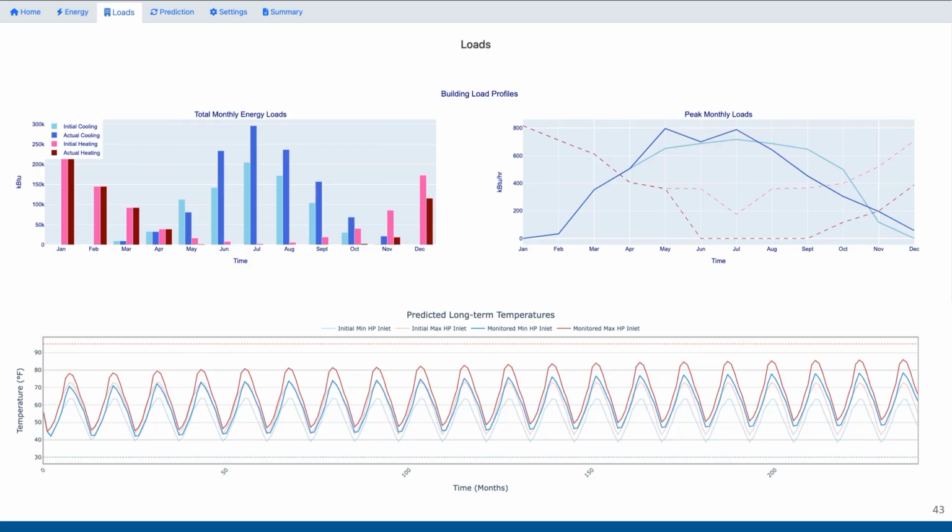that engineers can use. And then furthermore, your favorite ground heat exchanger sizing software uses algorithms to calculate the future design temperature of that ground loop. And I'll give you a little insider hint, those models are wrong, right? But it's a question of how off they are. They're generally conservative, but they're theoretical models. So as you collect more and more data, you can improve those theoretical models into empirical models based on that specific site and that specific building. So as an engineer, you can furthermore improve your practice by utilizing this.